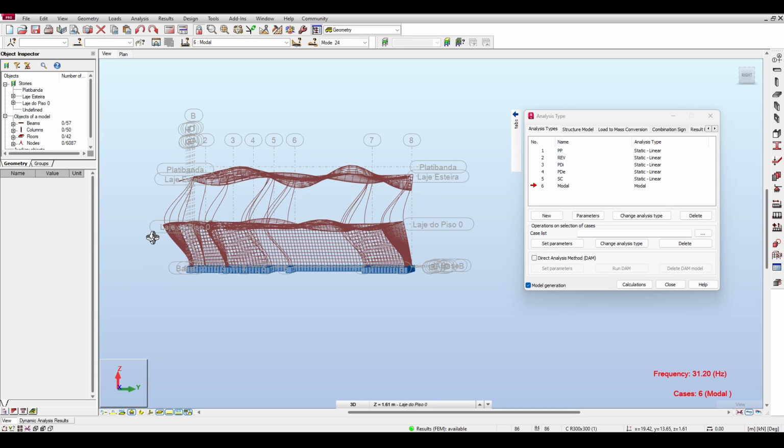You could add some springs here, just check out how they will affect it, if you want to model the soil with springs, but make sure that those springs are only compressive springs. So when you add them, they are only active if you compress against them, because soil cannot pull, it can only push. It cannot pull the structure back in place.